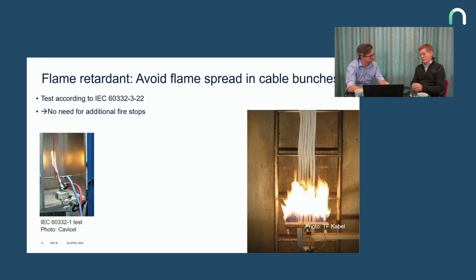But if I just have a cable and it's not 606 and it's not a DNV class ship, perhaps, then it's not necessarily gone through this test. Exactly. Then you don't know. Then you have to check every detailed specification.